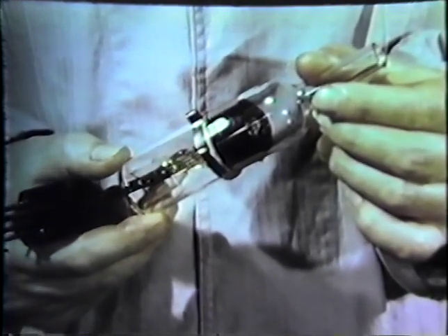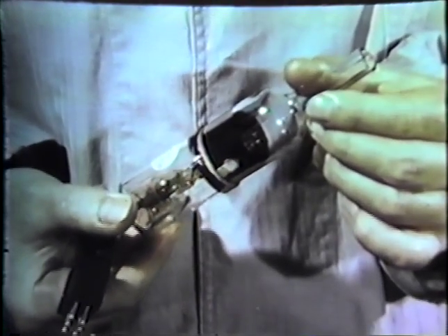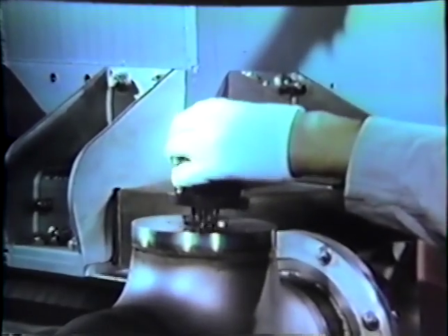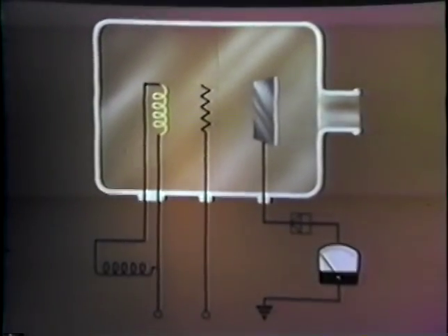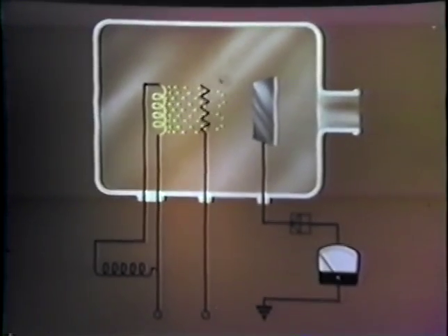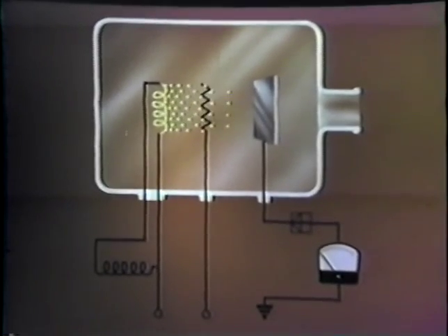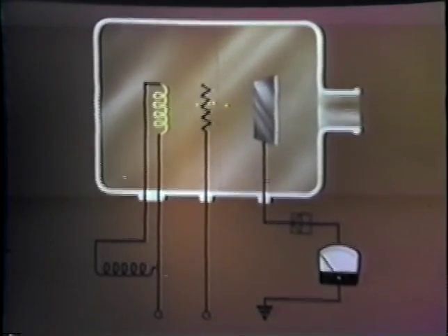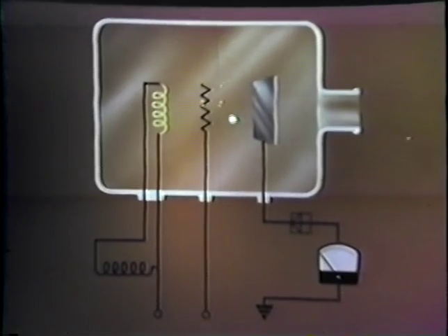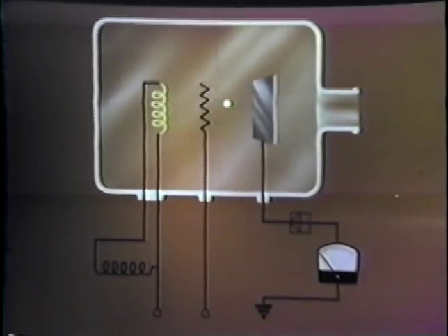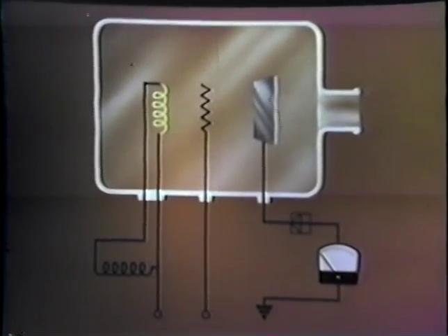For higher vacuum regions, ionization gauges are most widely used. They are commonly housed in glass tubes, but may also be made with a metal flange for permanent installation in a vacuum system. The gauge operates on a familiar principle. Electrons are emitted from a hot tungsten filament and are accelerated toward the grid. Some pass through and oscillate about the grid. During its flight, an electron may strike a molecule of gas in the tube. As a result, the molecule becomes ionized positively and is therefore accelerated toward the collector plate.